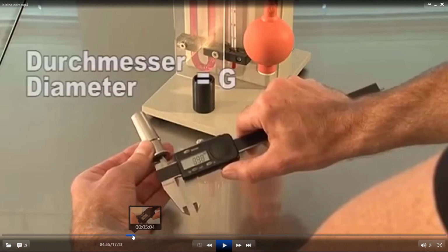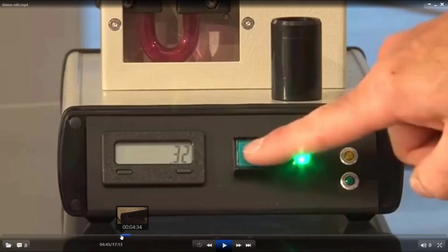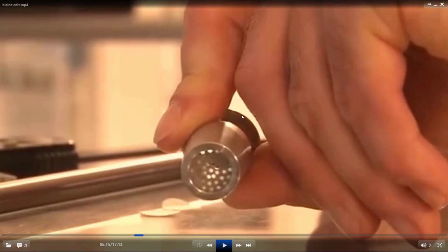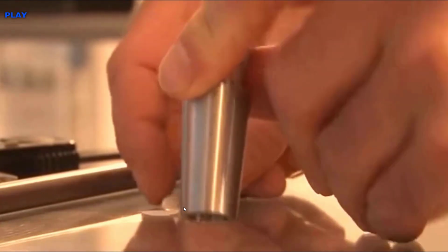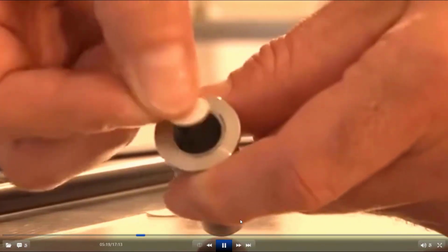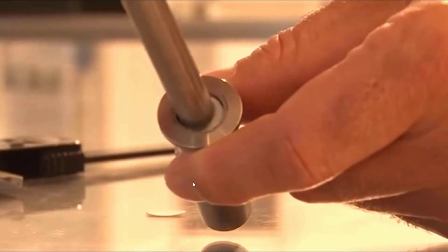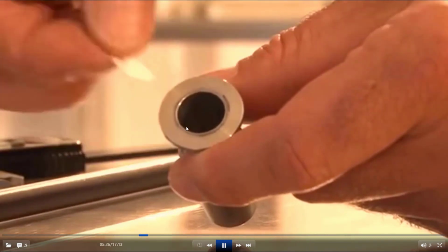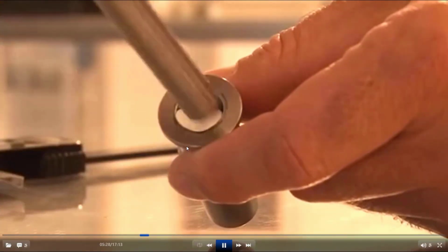The first step is to find out the volume of the column in which the cement would be inserted. The cylinder in which the cement has to be inserted has a perforated tube below it. Above the perforated tube, you first place the filter paper so that cement cannot pass through this perforated tube. Then you insert the cement, then your sample, and then your filter paper again.